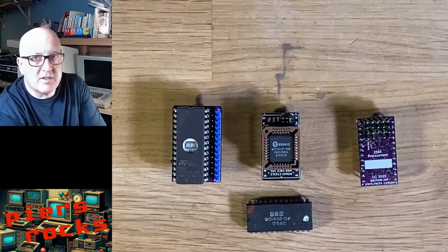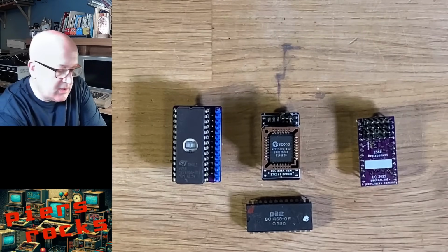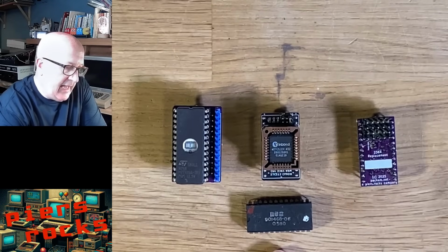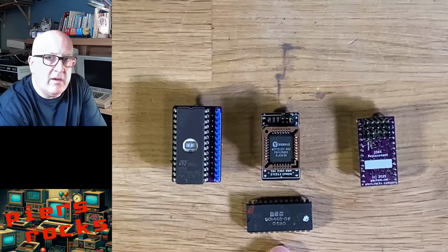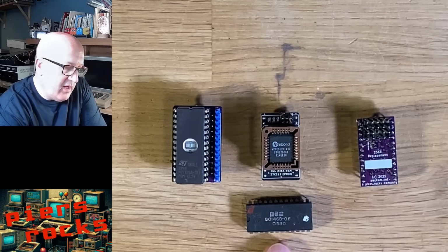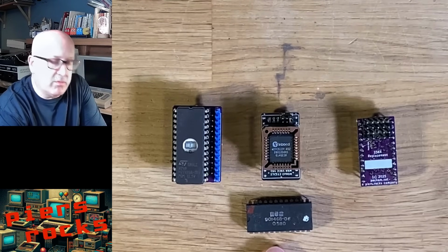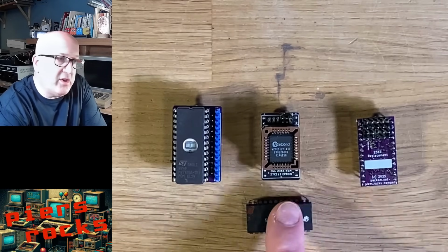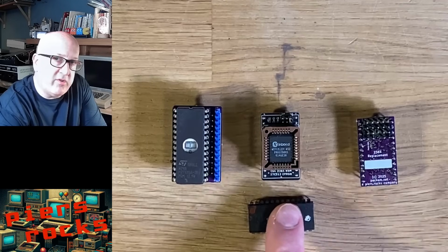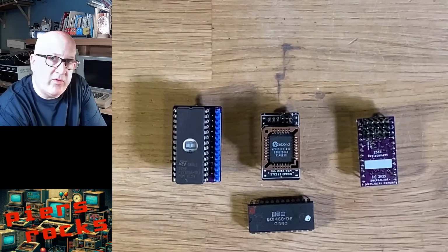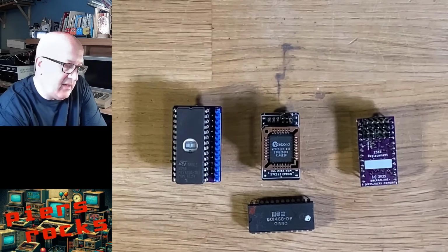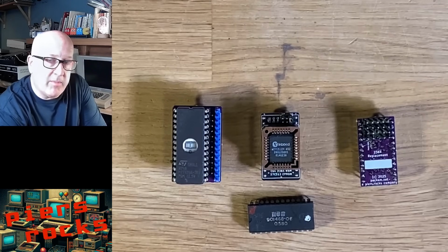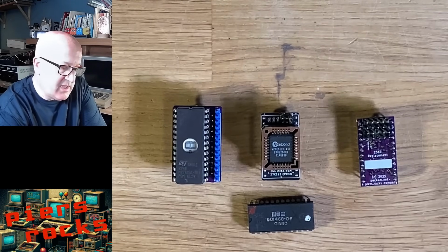One of the biggest frustrations I faced getting into retro computing is that I've hit a lot of failed ROM chips in my machines. And ROM chips typically come in three different flavors in the machines of the era that I'm working with. There's 2364 ROM chips, which are 8KB ROM chips with one chip select line. 2332s, this is an example of a 2332, which is a 4KB ROM chip with two chip select lines. And 2316, which is a 2KB ROM chip with three chip select lines.